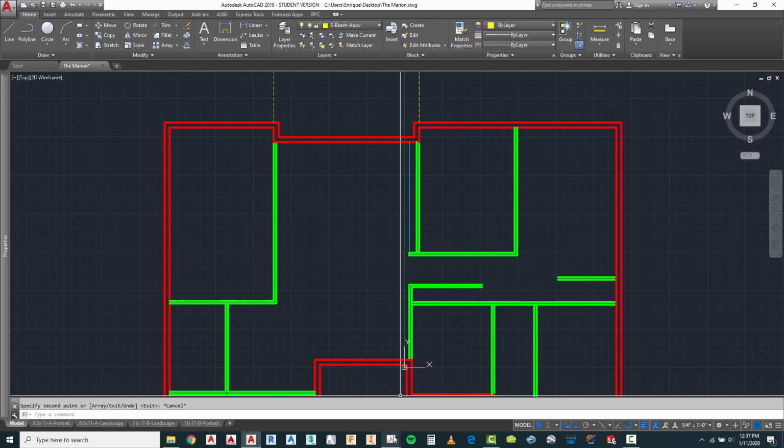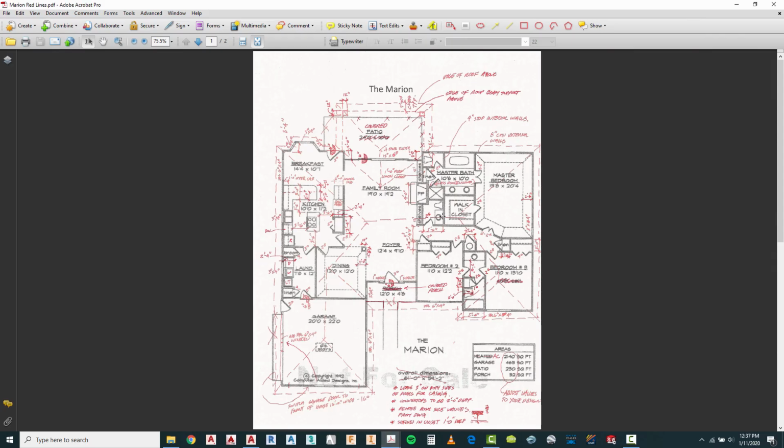Let's go back to our markup in here, and you notice that this bathroom right in here, which is a powder room, I wanted it 5 foot 6 inches wide, the same as this one in here. I've already got this wall, then I've got this wall laid out, so I can lay it out all the way up to be able to get the width of this. So let's start with those lines up into there.